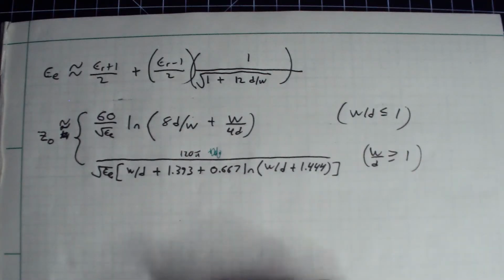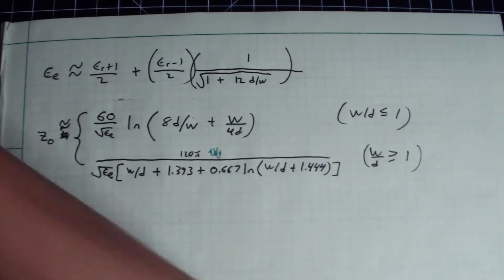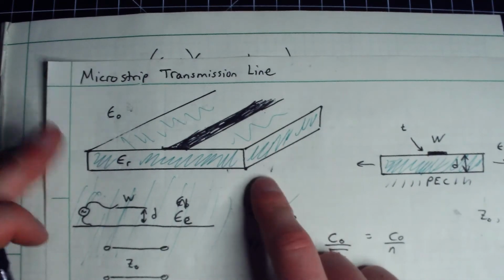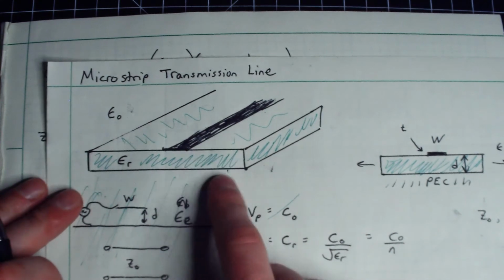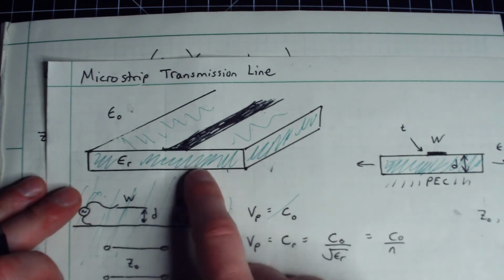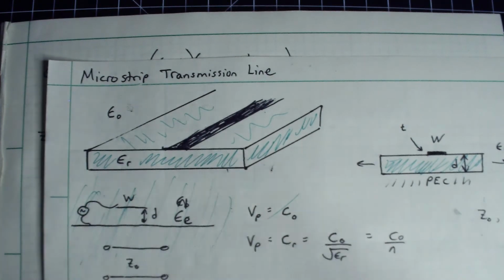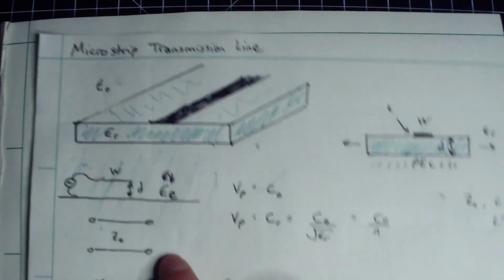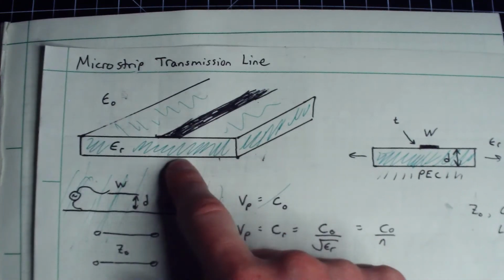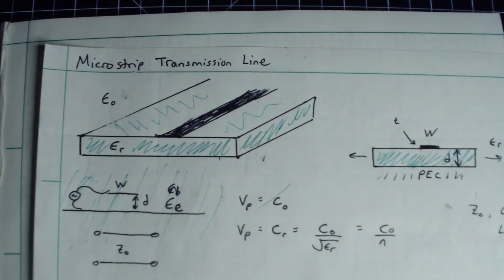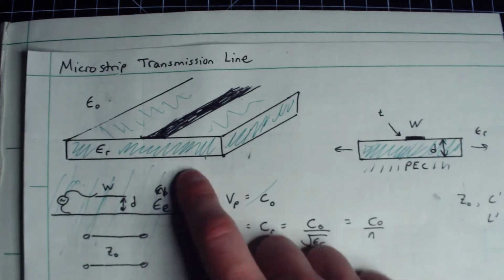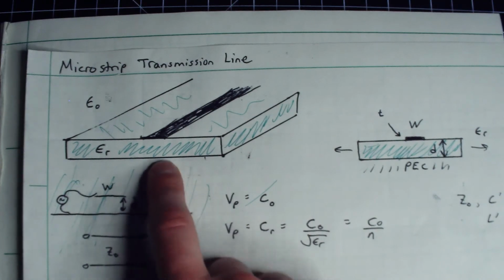But another important point is that, if we go back here to this geometry, we are looking at the low frequency transmission line equivalent circuit here. Obviously, as I go higher and higher in frequency, there will be higher order modes in this thing, which, as you can imagine, if it was difficult enough just to derive an approximation for the transmission lines, imagine how much more infinitely difficult it'll be to do a full field waveguide solution to this thing. So in that sense, just leave that to the PhDs. And honestly, if you're doing 50 terahertz signals in here, you probably shouldn't be using microstrip anyway.